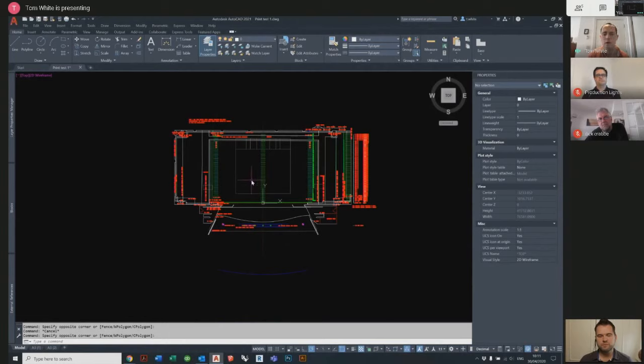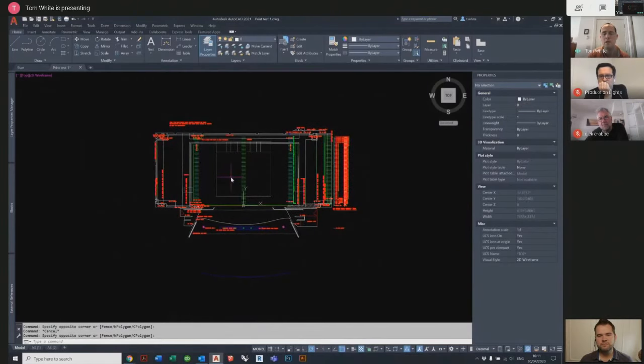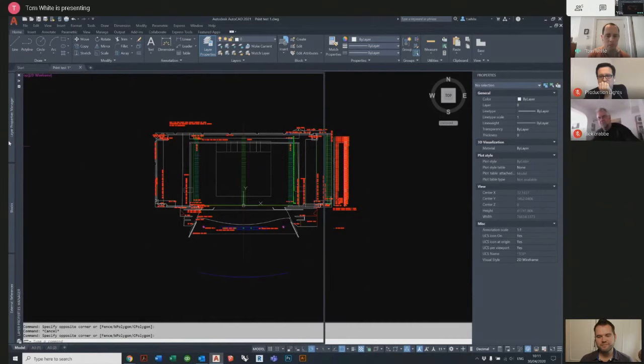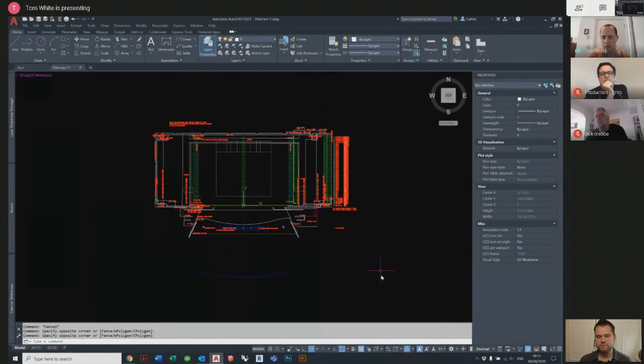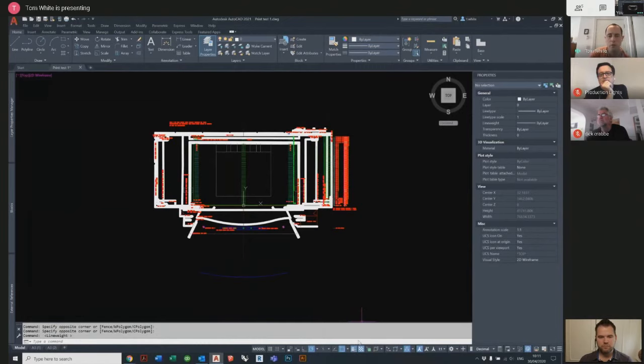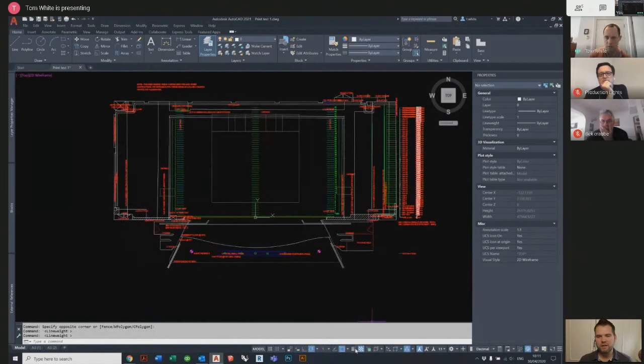So I desire to do a few checks on this. When I bring a drawing in such as this, I want to do a few checks. We can use the layer manager. You can see the colors of elements. You can see whether the line weights are thicker than desired. One of the things that is a good double check is down on the toolbar at the bottom, you can show or hide the line weight, and you can clearly see what was quite a pretty drawing to be something quite potentially unreadable when you produce the PDF.